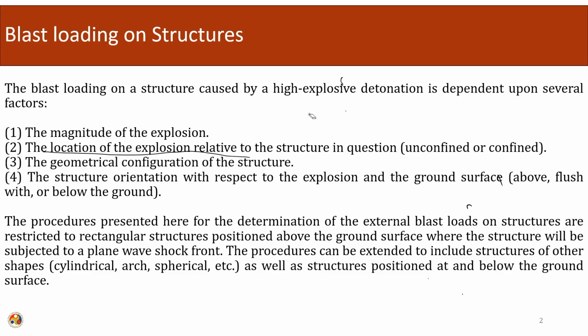Okay. The procedures presented here for the determination of external blast load on structures are restricted to rectangular structures positioned above the ground surface, where the structure will be subjected to a planar shock front. Okay. It means that whatever things we are discussing, we are discussing structures which are above ground. Okay. We are not discussing right now the underground structures. Okay. And the structure will be subjected to a planar shock front.